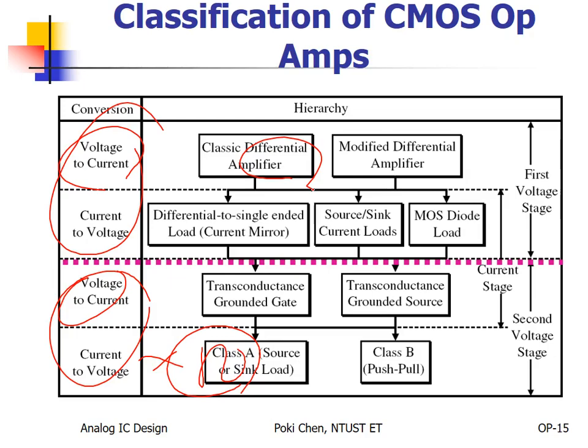Usually we have current mirrors, current source as the load. Why? Because to get enough RO, in the past we have real resistor. But to achieve 10K or even 100K, 1 mega ohms, it is really expensive. I mean, it is a really cheap area wasting. So gradually, especially for CMOS, we hate passive devices because they are bulky. I mean, they are really large.